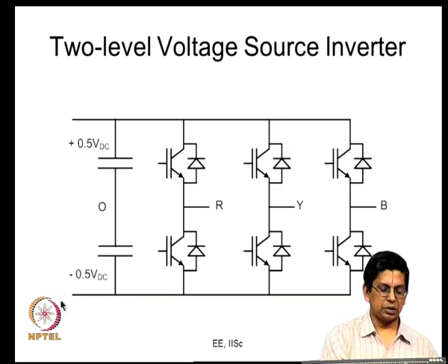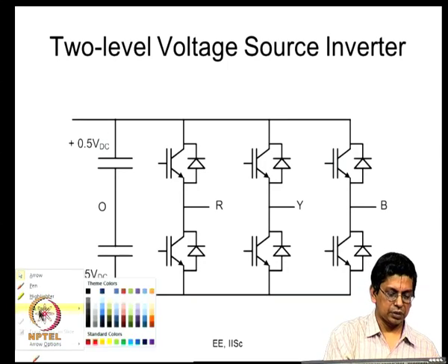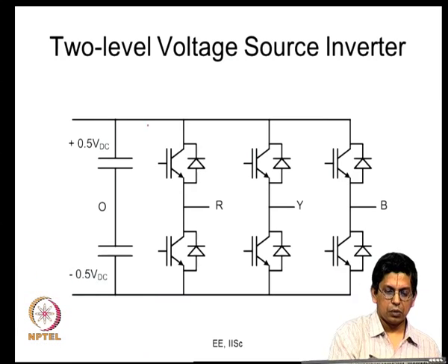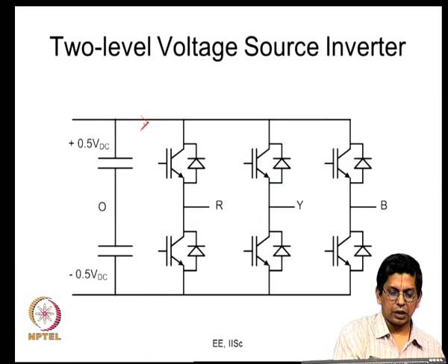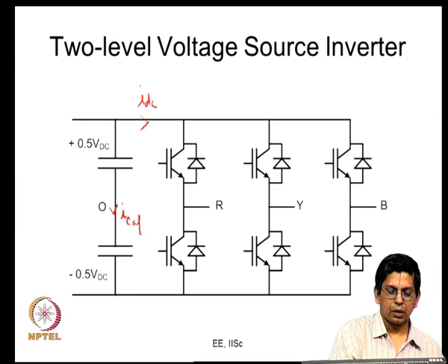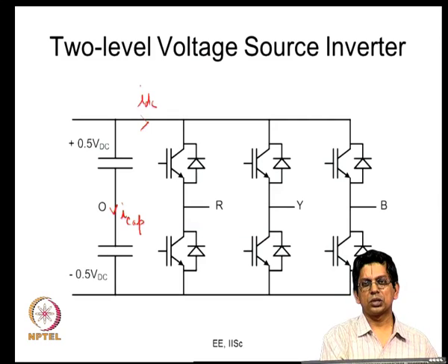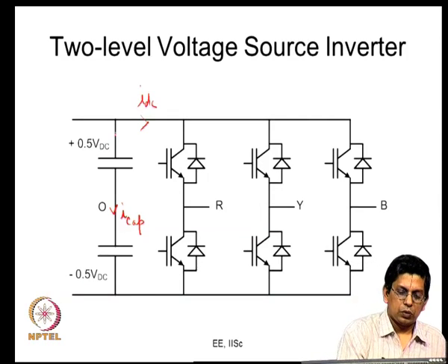We calculated this current, what we call I DC, and then the capacitor current. If you look at the various sources of losses, for example in the capacitor there are also losses, and that can be represented by what is called the ESR of the capacitor.